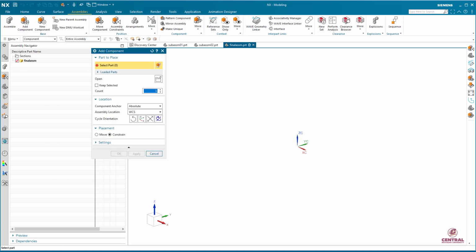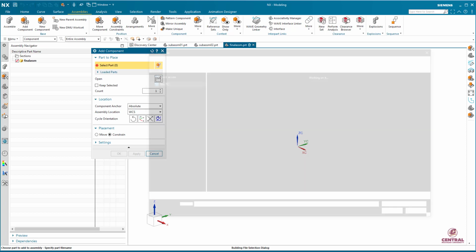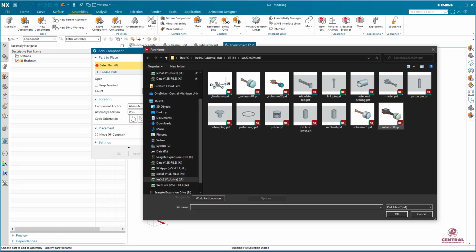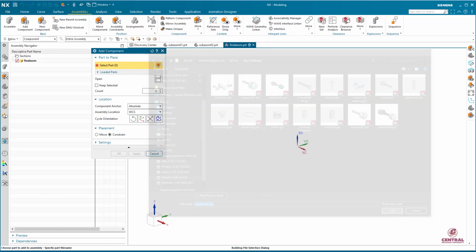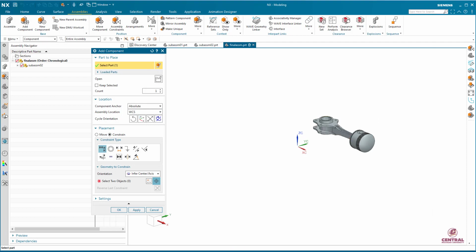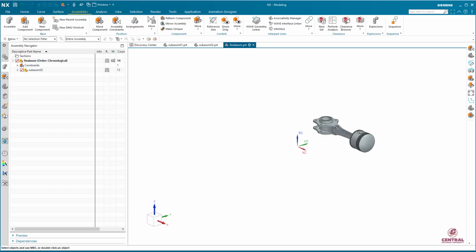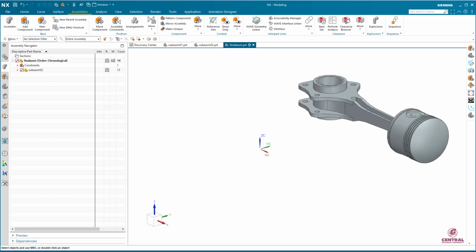The first one you're going to add is sub-assembly 2. One of them will be used, so it's not moving, it's stationary. The rest of them will be moving around. So okay, it will be there. All the color you had there just for the display in the sub-assembly is not going to be showing up, so don't get disappointed. And this time I'm going to of course fix the whole thing. There we go, so now it's fixed.